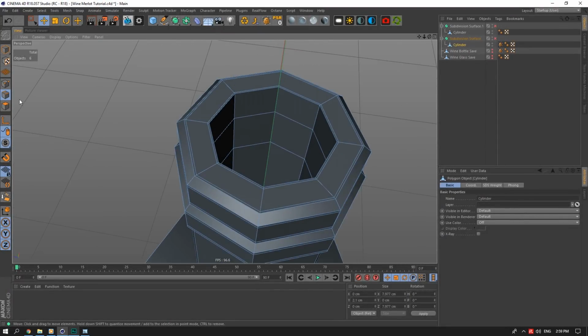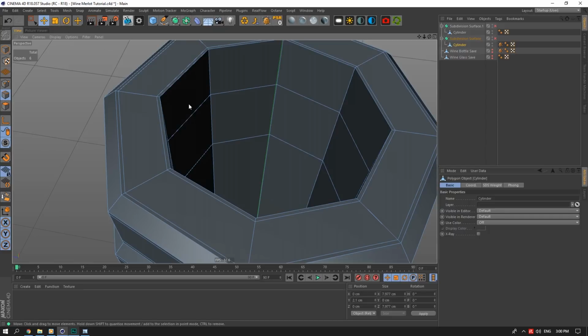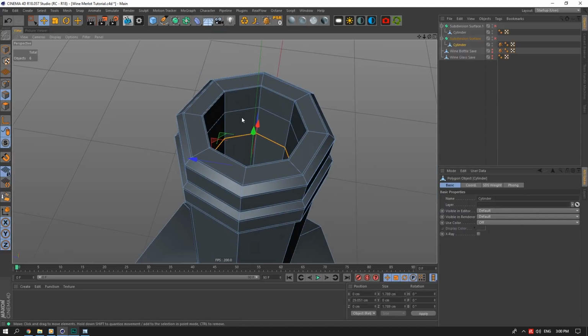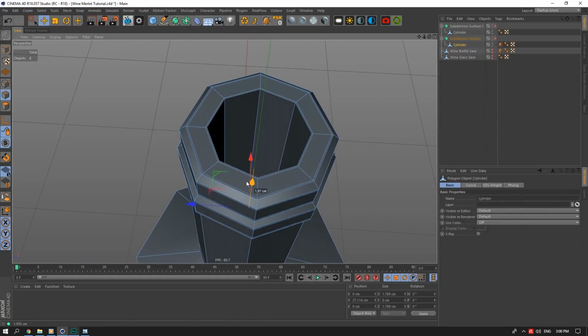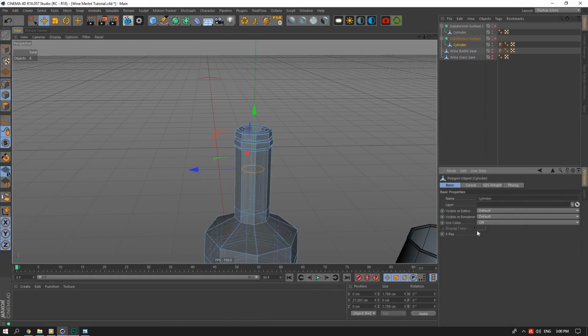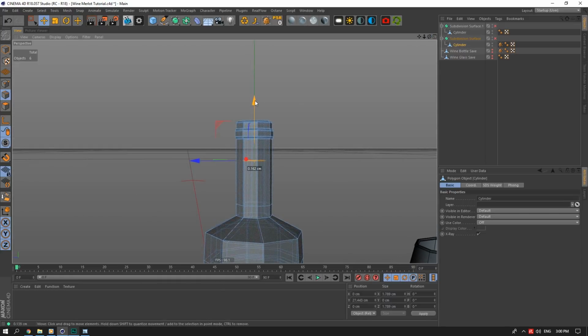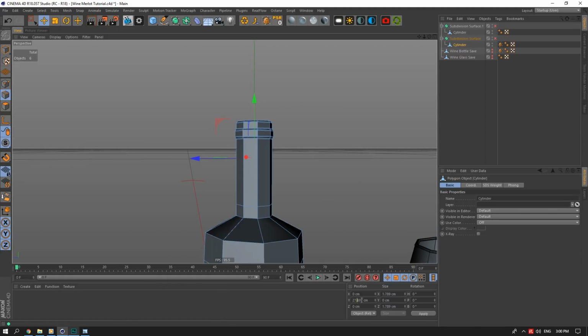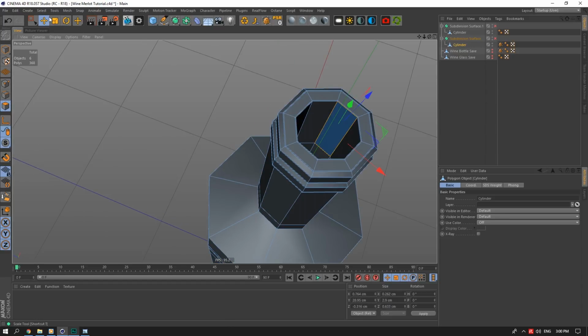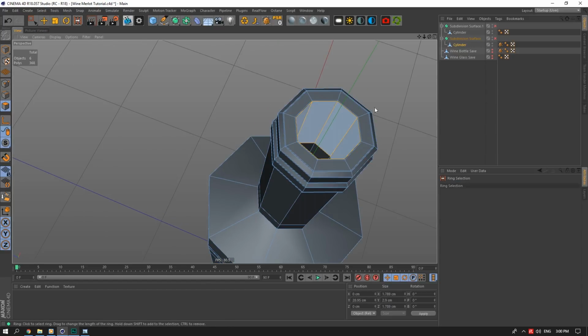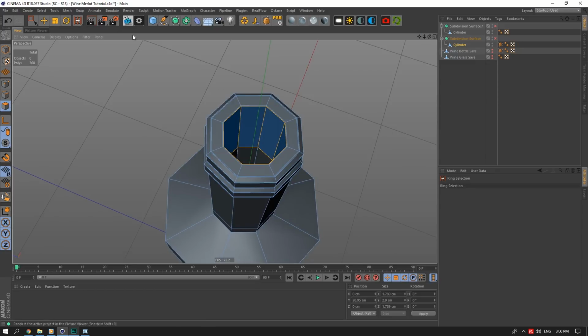So the cork, the way I did that is I just took, this is why I left these lines in here. Like I said, my bottle is fully closed, so I can't actually go and check it in there. But I think it'll be around that thick, around that deep inside the bottle, somewhere there. And if you want, you can go and round these off to maybe 0.5, just to make your things a bit more even. And then I'm going to go and ring select. All our normals and stuff are the wrong way around, but we'll sort that out now.